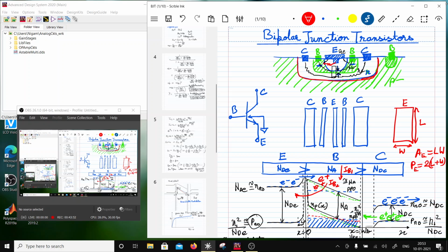Right. Now the thing to understand here, because this has caused a lot of damage in businesses, is that you cannot expand the width to be twice. So for example, if I do this, and this is W and this is L, and I say I'm going to make twice W and half L, this is the same area as here, but these two transistors are not the same.